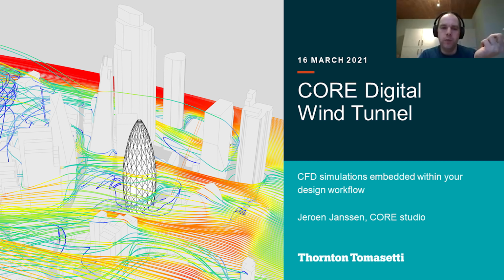How does it perform with wind? So you could actually just run a 15-minute simulation, and it will give you a better answer than at the moment the code requirements, which is quite rigid, right? It's based on a square building or a cylinder or a flat football stadium, which is a dome or something like that, something typical, or a simple spreadsheet at the moment. But you can get actually a much more detailed answer earlier on, and then gradually zoom in. And then at the end, maybe you do a verification with a specialist consultant together.